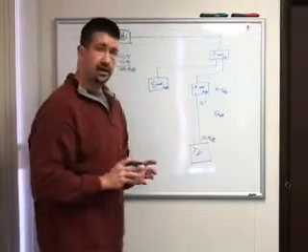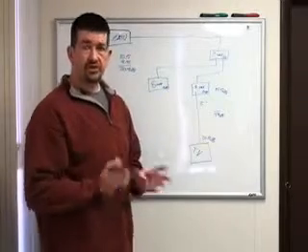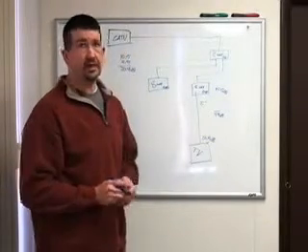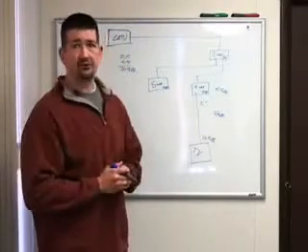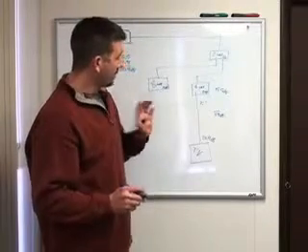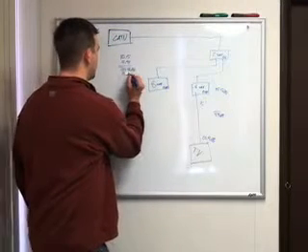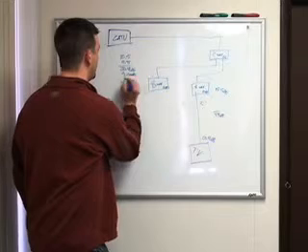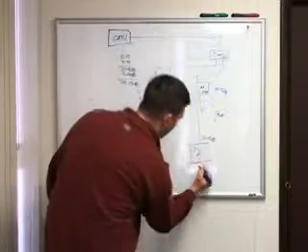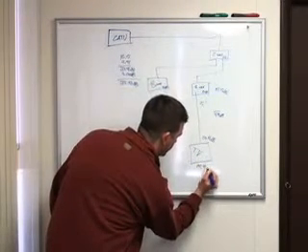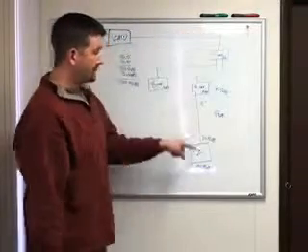Now we need to calculate what signal level we want at the TV. Most guys engineering systems shoot for 5 dB. It's relative, but I would say 5 dB is a safe number to shoot for. So we're going to add 5 dB onto this 20.41. 5 dB plus 20.41 is 25.41 dB. So 25.41 dB is the total signal that we need going to the input of this 2-way to give us 5